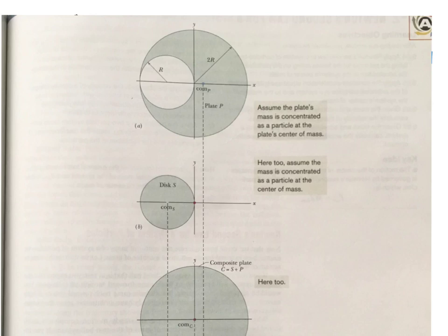Again, why is the center of mass at the origin here? Why isn't it like here, where it's between these two dotted lines? Because as soon as I punch out a portion of this, look at my center of masses. One is to the right of the origin, one is far to the left, yet the center of mass is now the origin again. How is that possible? Is there still areas above and below the punched out circle that move the center of mass to the left? The above and below actually only move the center of mass up or down. Yeah, but they are to the left. The part above is still to the left.